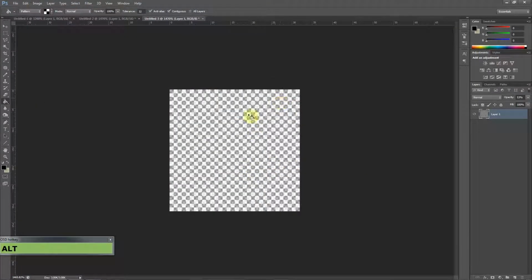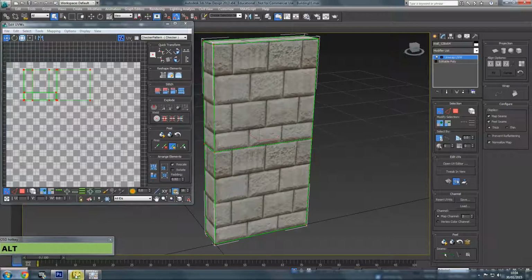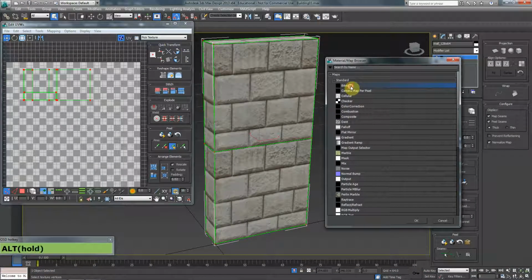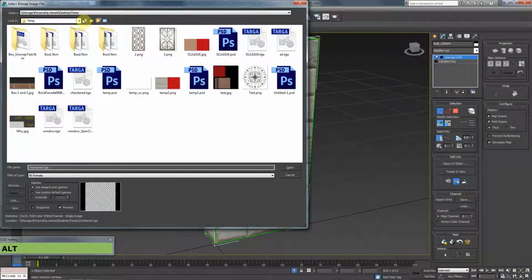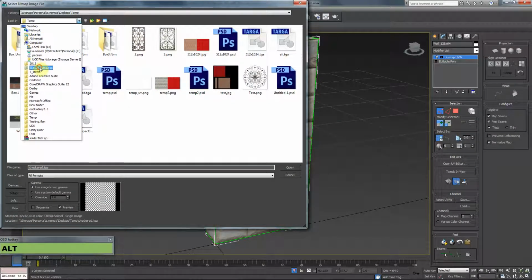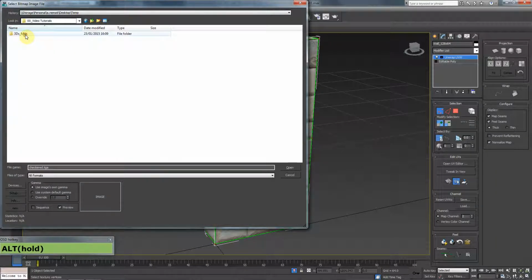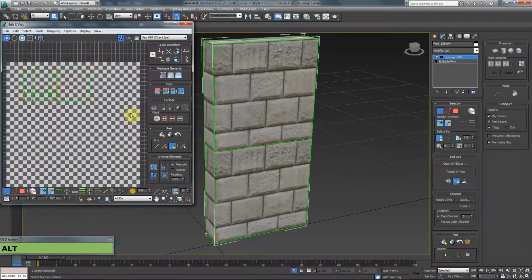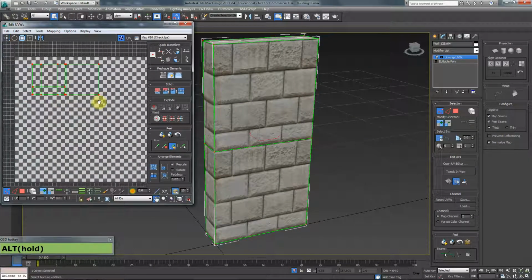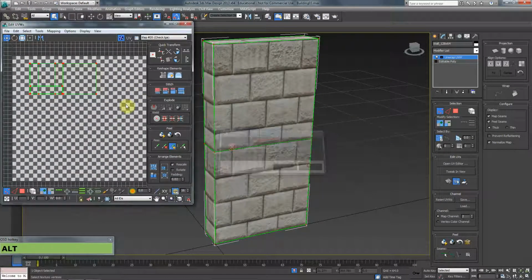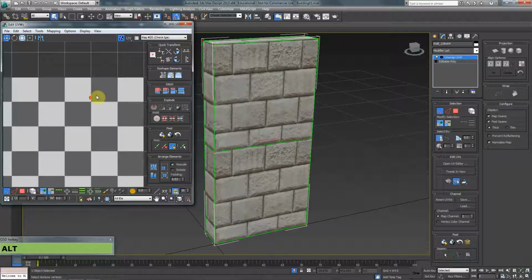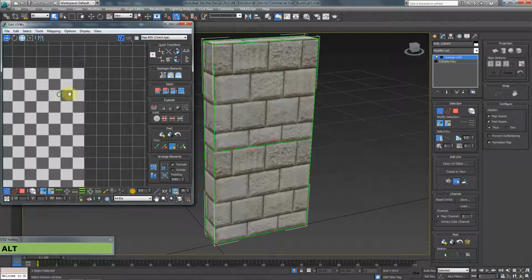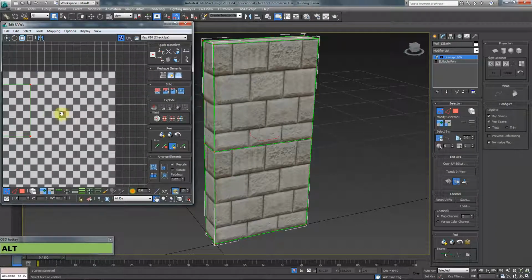32. Okay. And then inside 3ds Max, I want to pick that texture. So bitmap, and we want to find our folder again, in my case being here, the TGA check. Now what I see here is my checkered box, and if you look at this, each of those boxes that I made fit perfectly in here. So each of these right now are basically a pixel.